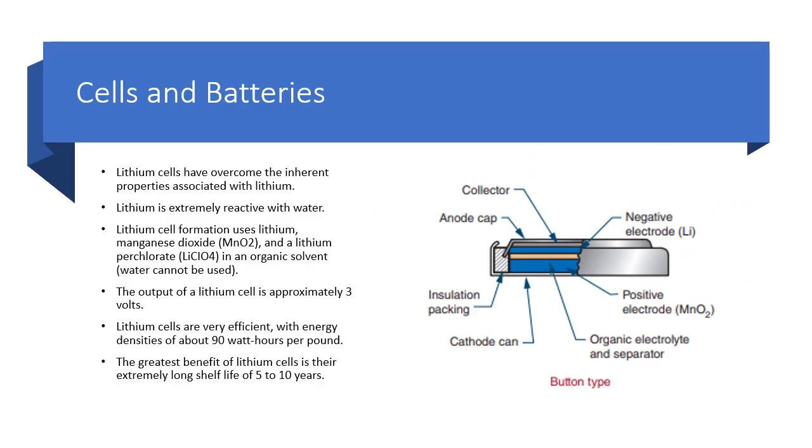Lithium cells, as in figure, have overcome the inherent properties associated with lithium. Lithium is extremely reactive with water. Lithium cell formation uses lithium, manganese dioxide, MnO2, and a lithium perchlorate, LiClO4, in an organic solvent.